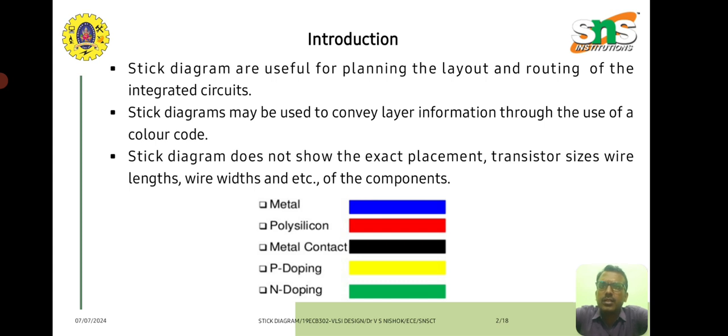Stick diagrams are useful for planning the layout and routing of integrated circuits. Stick diagrams may be used to convey layer information through the use of color codes. A stick diagram does not show the exact placement, transistor size, wire length, wire width, etc. of the components.